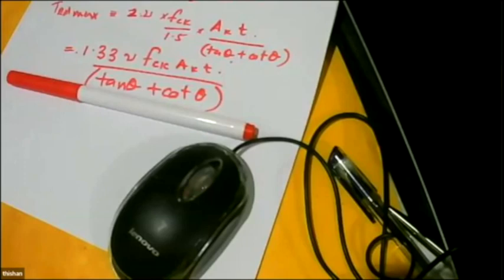So always secondary beams will be in simply supported mode. And how we achieve that in practice is we provide only two numbers of 12 millimeter bars at the top of the secondary beam. The moment you do that, all the secondary beams are simply supported, so no torsion will be transferred to the main beams. Is that clear? Yes, that is clear.